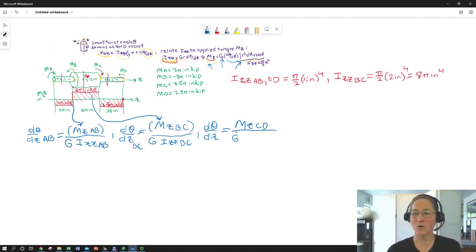If you're joining something with a collet or a collar or some other kind of complicated fastener, everything we're doing kind of goes out the window, because you're going to have another material, a different dimension, different considerations. So this very simplistic derivation would no longer apply. The only thing that would apply would be a very fine butt weld, where you've literally just abutted the two materials without any significant changes other than the change in radius. Because of that, G is going to stay the same most of the time.